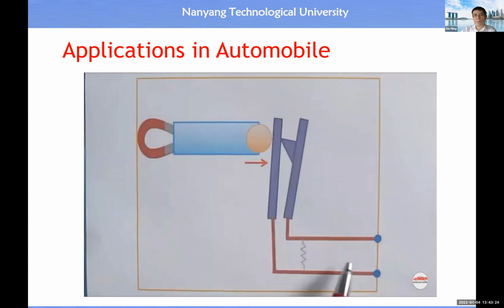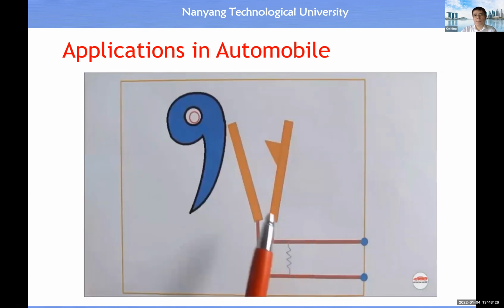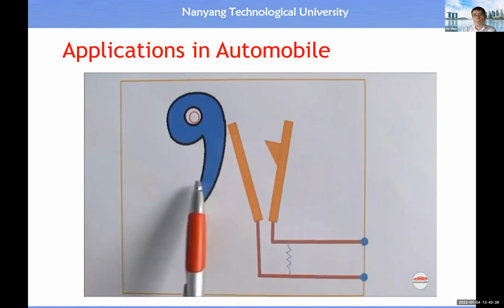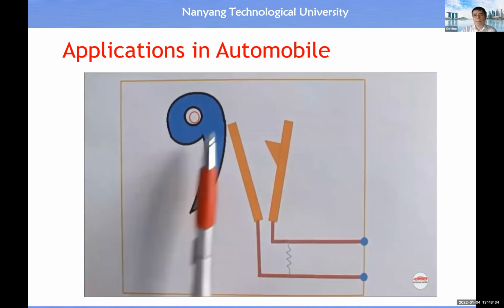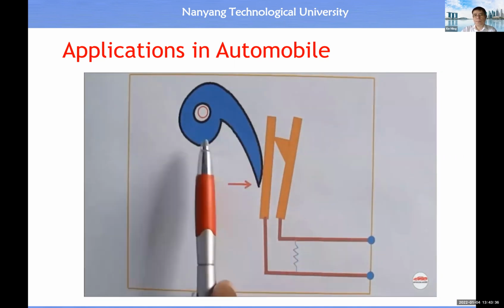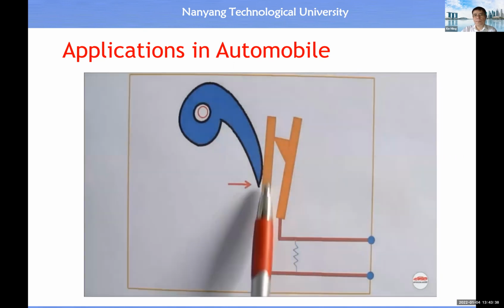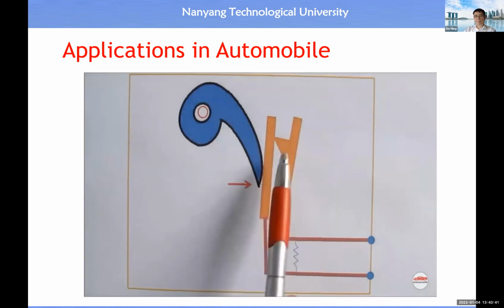This is the kind of sensor that's in my car right now. It basically consists of a small cam, as well as two contact switches and a diagnostic resistor. Driving along normally, this cam is free to bounce back and forth. However, under rapid deceleration, the momentum of this cam is enough to overcome the spring force of this switch, sending a short circuit out to the SRS computer.